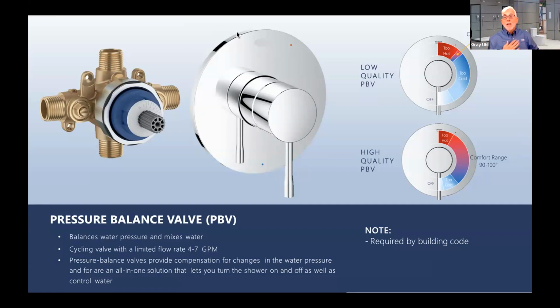When I was a kid, I was the middle of 5 boys, and pressure balance didn't exist when I was young. My brothers thought it was very funny. If I was taking a shower, they thought it was very funny to run in and flush the toilet. What that would do, the toilet would demand all the cold water, the pressure would drop on the cold side, and nothing but hot water would be delivered to me in the shower, and I would get scalded, which is pretty funny, I guess, but pressure balance eliminates that. It's a safety feature and a good one.